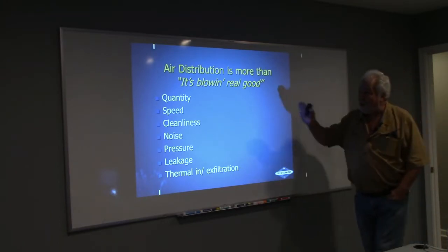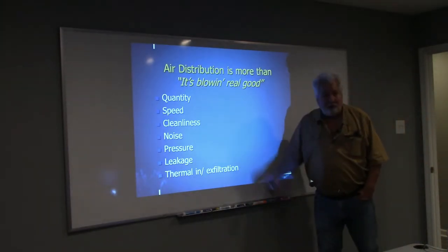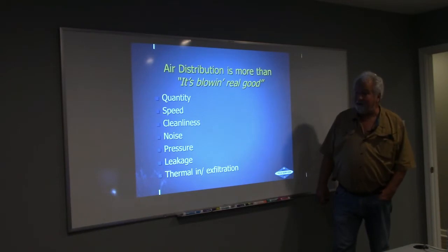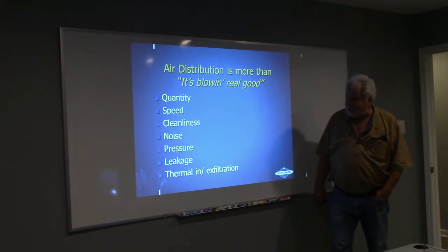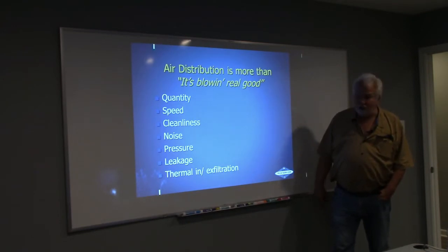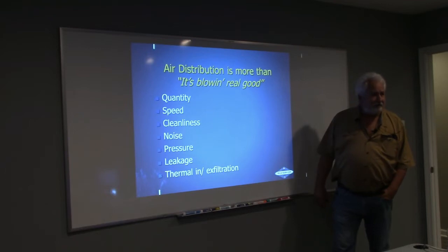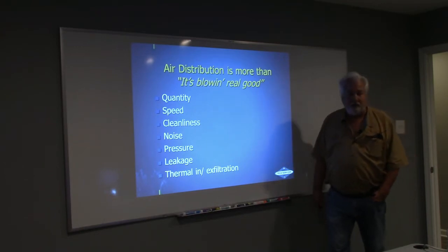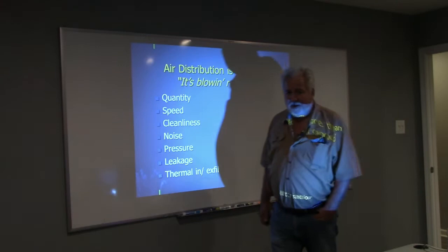I need to know quantity, I need to know speed, whether the air is clean, whether it's noisy, what's the pressure differential, what's the static pressure, the leakage, is the ductwork all leaking on the supply or return, the thermal infiltration or exfiltration, does it have insulation on it? Is it wrapped well, or is it that old paper wrap stuff that basically has no insulation at all?